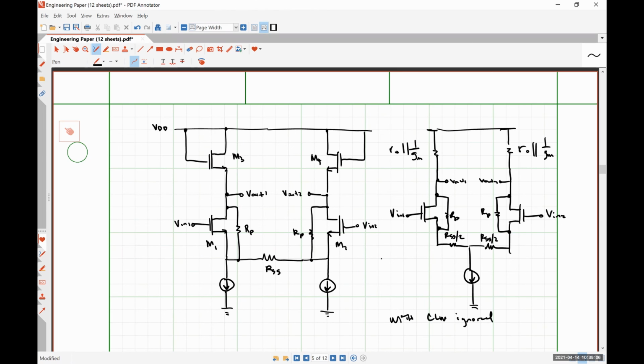For a diode connected, let me go back to my notes where we reviewed transistor current sources and diode connected transistors. Okay, no, I see what you're talking about. So for the diode connected BJT, there would be an r pi in parallel with r0 in parallel with 1 over gm up top. Yeah, you're right.